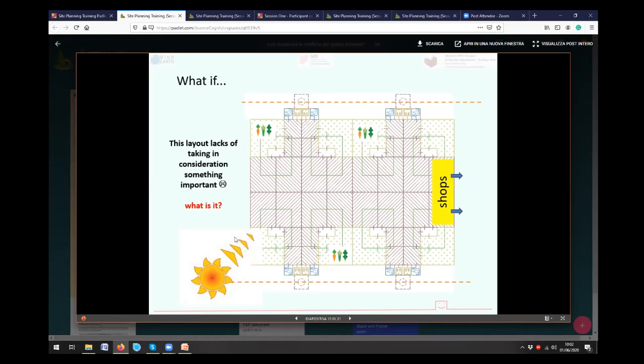This is the main important issue over here. Of course, there are others, but it is the proper way we place a structure like this on the ground. Because if this is south and I have the sun over here, this shelter will be privileged, because they're going to have sun in winter, so they're going to be a little bit warmer in winter time. Of course, they will have to be protected in summertime, but that's another story. They will have better illumination if they have windows looking inside the courtyard. If the bottom of the screen is south, we have good illumination, good insulation, which is good. But the shelters on the north will be less illuminated because they will not have direct sunlight.